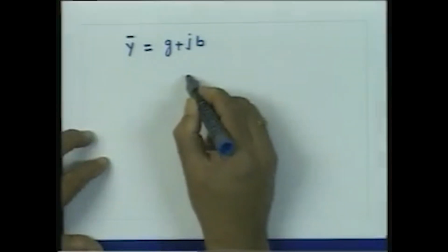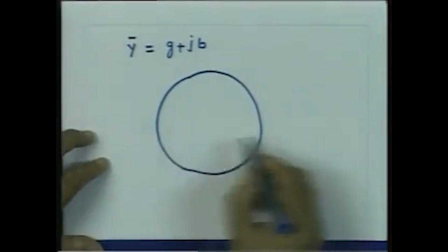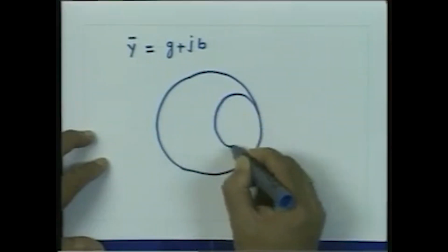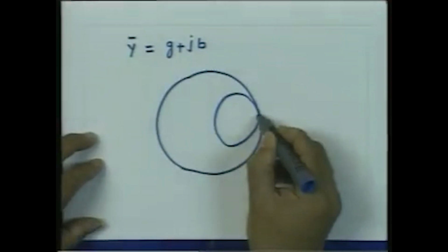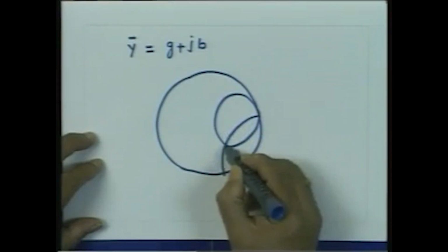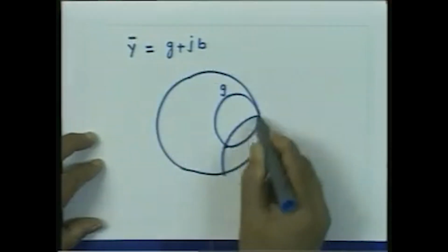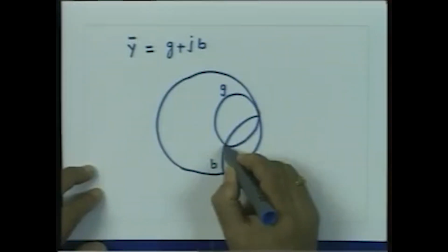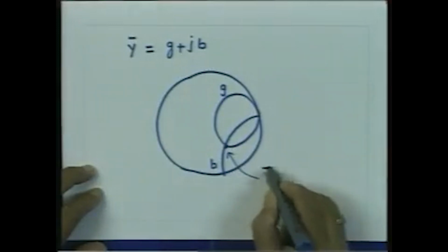Now, in this case, as we mentioned earlier, we keep the Smith chart same. So, let us say this circle which we have here corresponding to this is the G value, and a circle which passes through this, let us say this value is the B value. So, this is the G value, this is the circle which is the susceptance value. So, this is the point which is y bar.